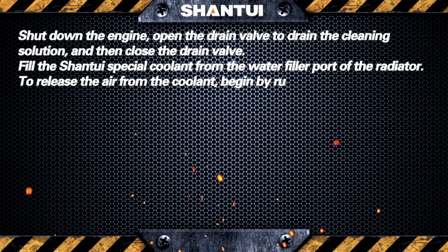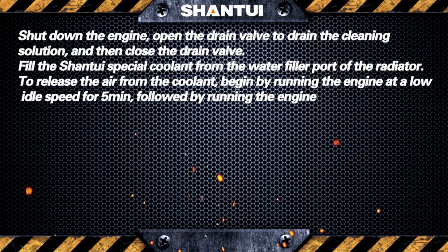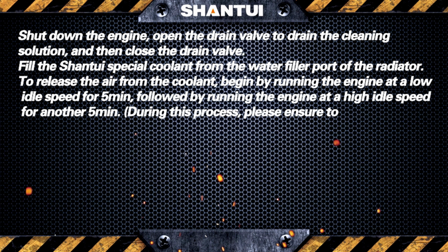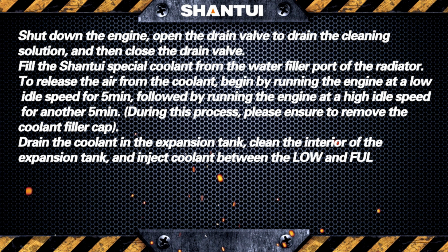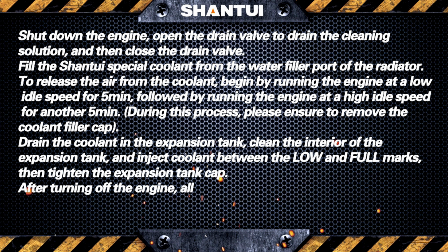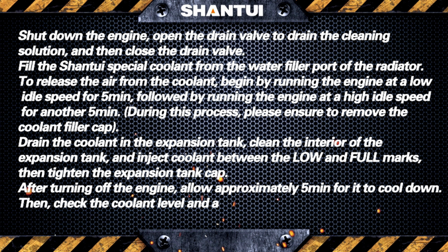9. To release the air from the coolant, begin by running the engine at a low idle speed for 5 minutes, followed by running the engine at a high idle speed for another 5 minutes. During this process, please ensure to remove the coolant filler cap. 10. Drain the coolant in the expansion tank. Clean the interior of the expansion tank and inject coolant between the low and full marks, then tighten the expansion tank cap.